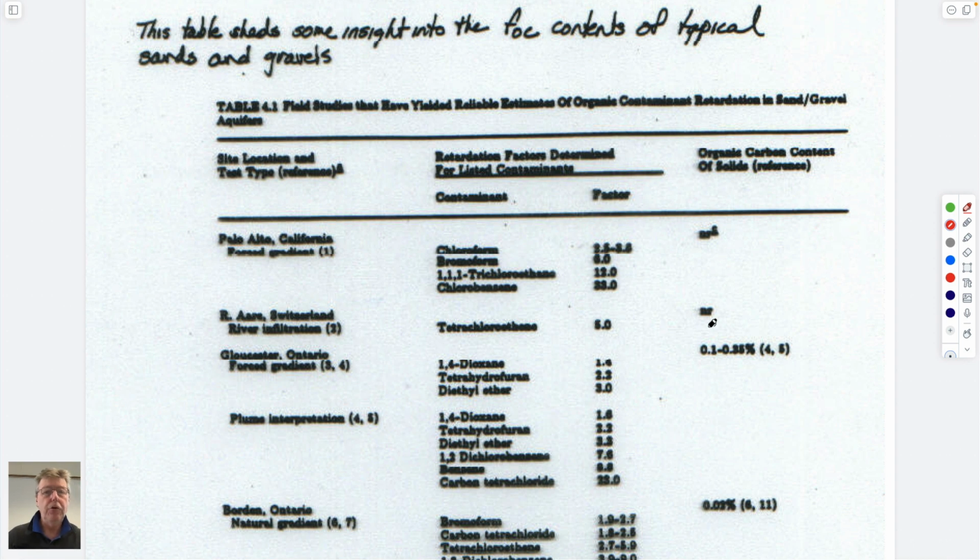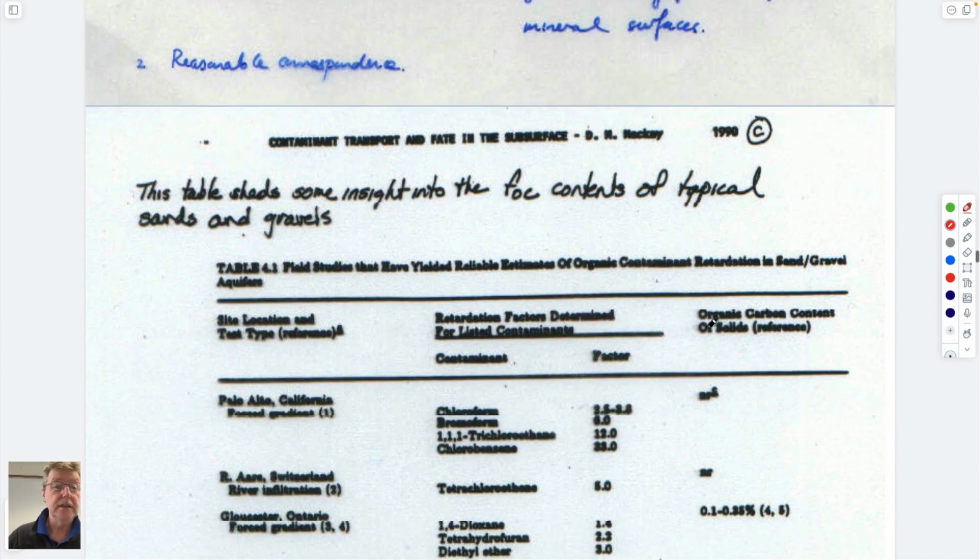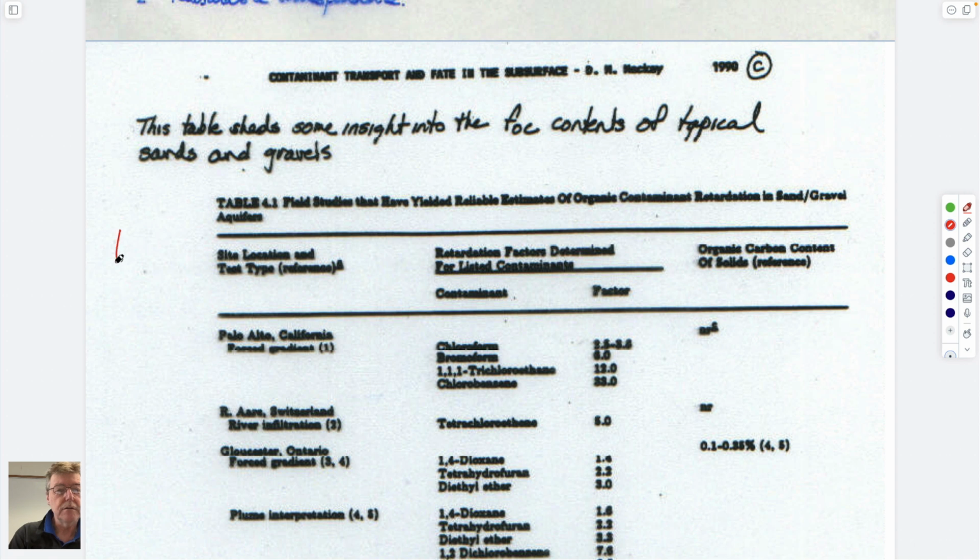So we said that before, the one way that you could get KD, if I draw it here, is that you take, that's a good question. So, remember we said that you take a sample and you'd pour in something at a concentration C and you'd measure C star on here. And so you do that for one data point. Concentration in the water, concentration on the solid, which is removed from the water. You do it once. You're going to create the absorption isotherm. And get the slope of that. That's all.